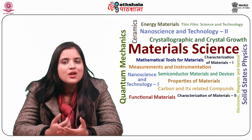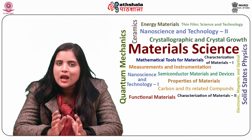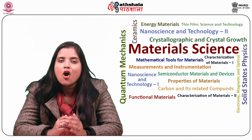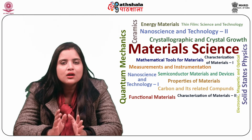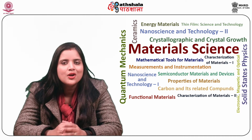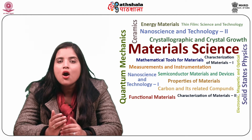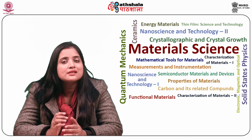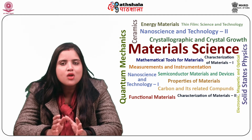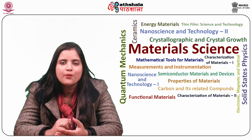The inert gas evaporation condensation processing, wherein nanostructured materials are produced by the evaporation of a metal source in an inert gas, is an extensively employed technique to synthesize very fine metallic particles or nanoparticles since 1930s. This synthesis protocol has been followed for producing crystalline nanoparticles in powder form.